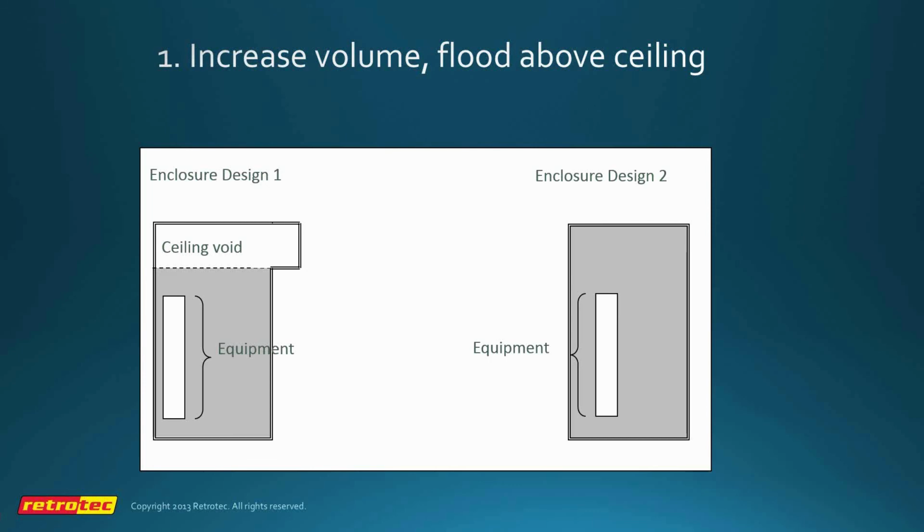This is more true with NFPA, because the concentration that we have to hold with NFPA and ISO is 85% of design, so that only allows us to lose 15% of our agent. With ISO, because of the 90% of enclosure height, we have to hold 90% of our agent for descending interface. So descending interface for ISO is much, much more conservative.